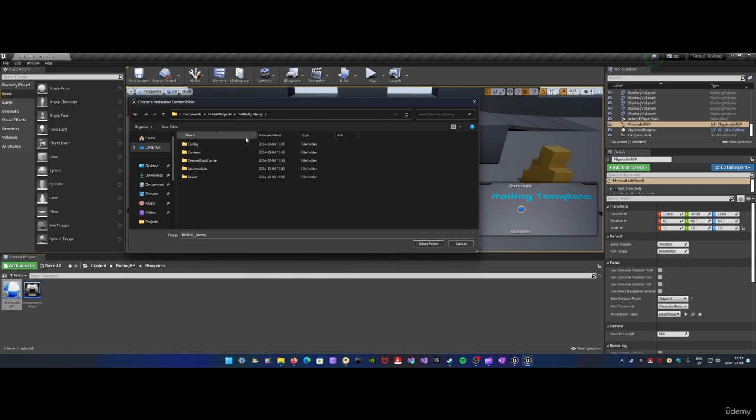And make sure to go into your project and select the contents folder. You cannot really select any other folder. You should always select the contents folder when migrating assets. If you choose any other folder, I cannot guarantee that things will go correctly. Okay? So always go for the content folder. So I'm going to click on select folder.